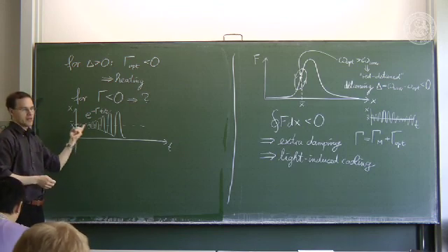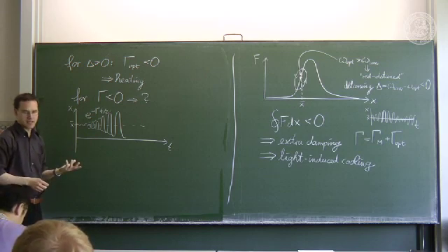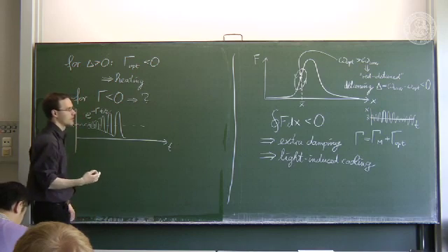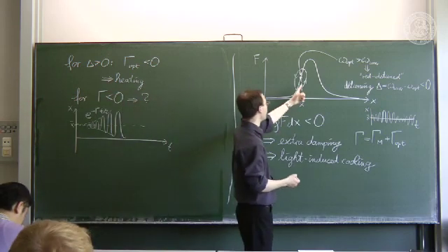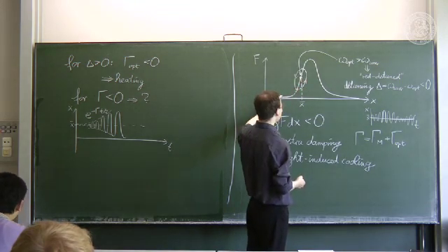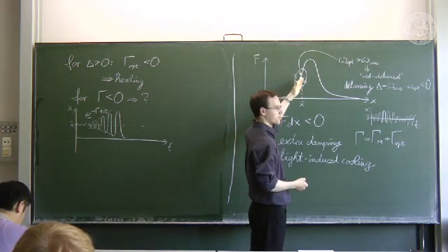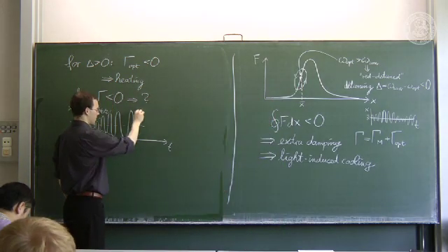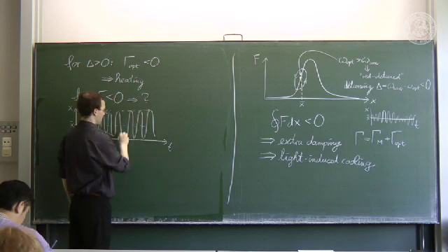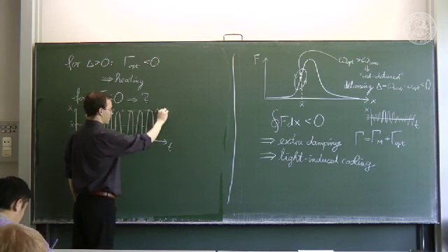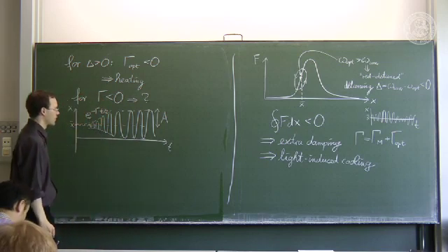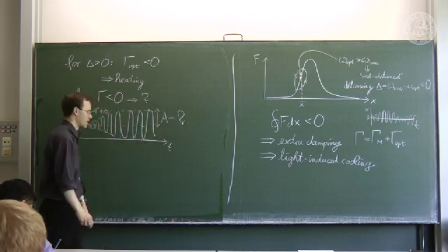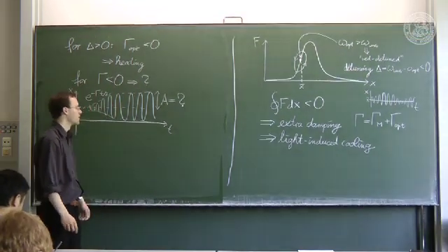Now that doesn't go on forever, otherwise the mechanical system would break. But even before that happens, some nonlinear effects kick in, because at some point, for example, the motion becomes so large that the amplitude gets out of the range of the slope, and then the motion saturates. One of the questions you can ask is, obviously, what is the value of this amplitude that the system saturates to?